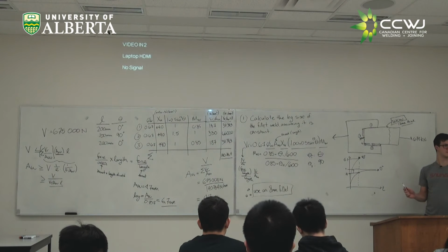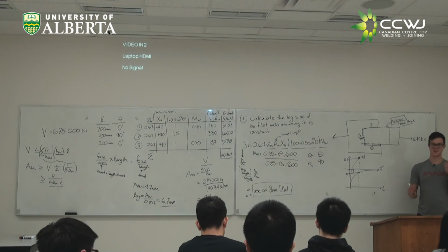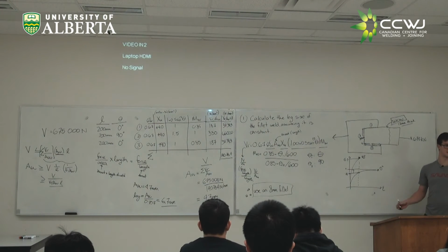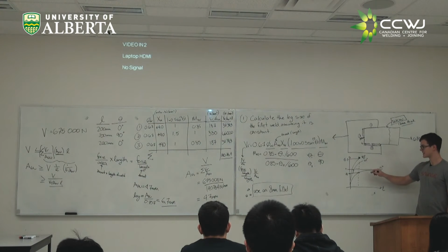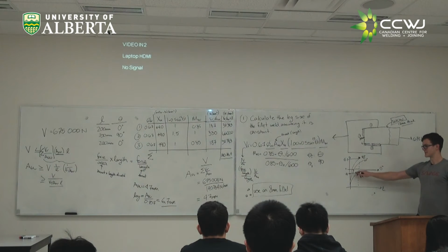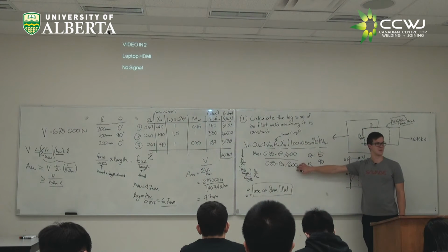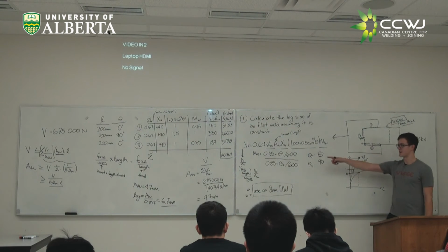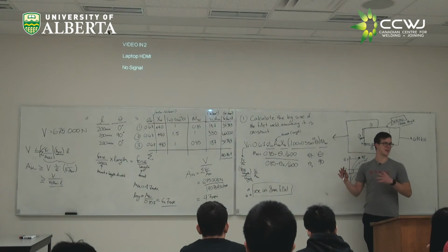Does everyone see that? It gets a little bit more complicated if you start to deal with welds that aren't at 0 and 90 degrees, where this is still true, but it's more complicated to draw it out and see where those factors come into play. Because if you have a weld that's somewhere in between, something like 60 degrees, then this is no longer 1 or 1.5, it's somewhere between. We still assume that there's some knockdown, but then we have to use the more complicated form of this formula. But it's all based on people doing tests, getting these results, and coming up with what is probably not a perfect representation of the experiments, but it's a way of getting close to an approximation.